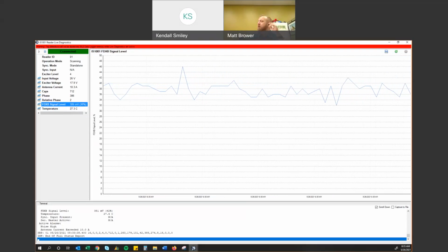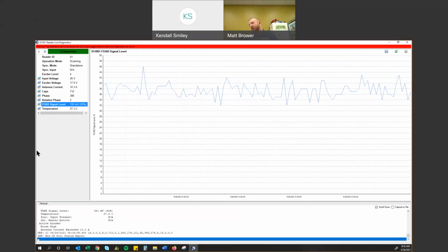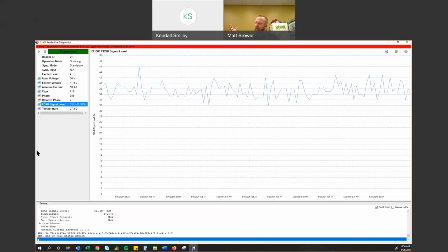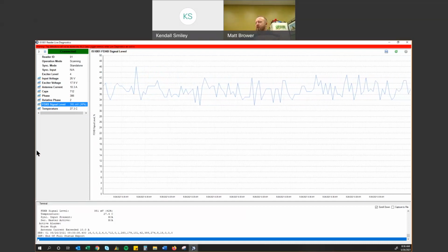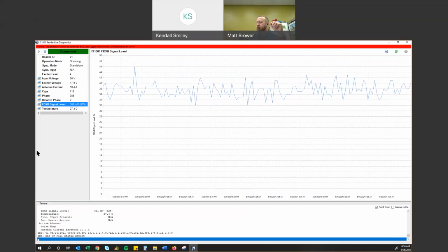The fact that this is doing it through Bluetooth is actually pretty amazing. We've played around with this with Biostat for a while. The biggest reason is this is a lot of information that's streaming straight to your computer via the Bluetooth, and it took a little time for us to understand that. But one thing that's cool about the Bluetooth feature is computers can be kind of noisy. We've had issues in the past where people have plugged their computer into their reader, and all of a sudden the reader got really noisy. That noise was actually feeding from the computer through the USB cable into the reader. So this eliminates any of that dirty computer noise.